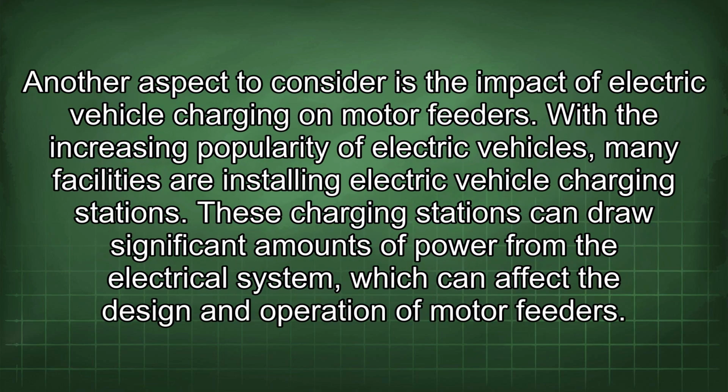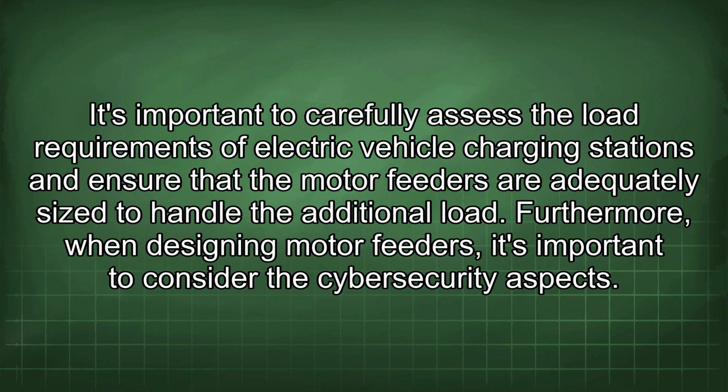Another aspect to consider is the impact of electric vehicle charging on motor feeders. With the increasing popularity of electric vehicles, many facilities are installing electric vehicle charging stations. These charging stations can draw significant amounts of power from the electrical system, which can affect the design and operation of motor feeders. It's important to carefully assess the load requirements of electric vehicle charging stations and ensure that the motor feeders are adequately sized to handle the additional load.